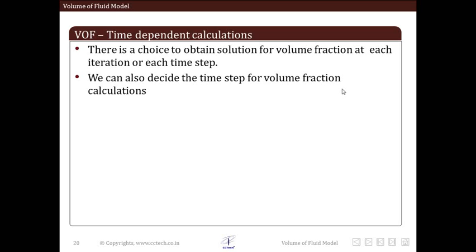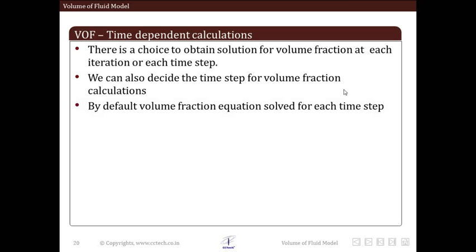We can also individually decide the time step for volume fraction. That is, the time step that is used for volume fraction equations can be different from the time step that is used for other equations like momentum or continuity. The default setting is that the volume fraction equation is solved after each time step. That is, after each time step of the continuous flow equation.